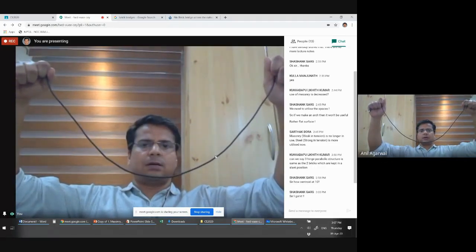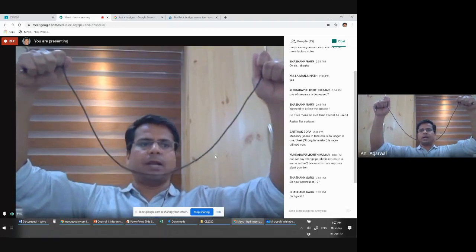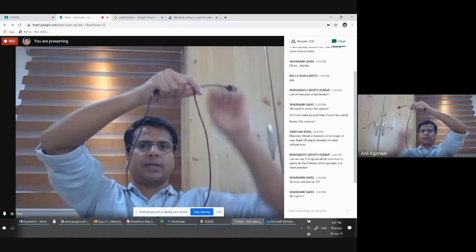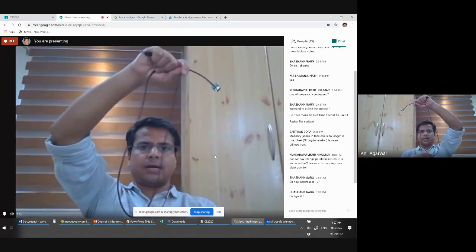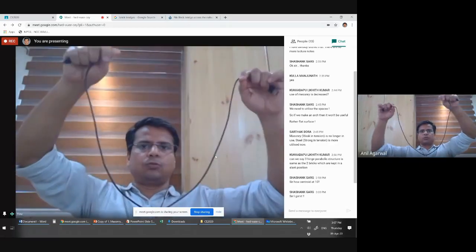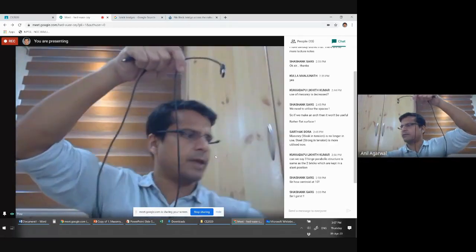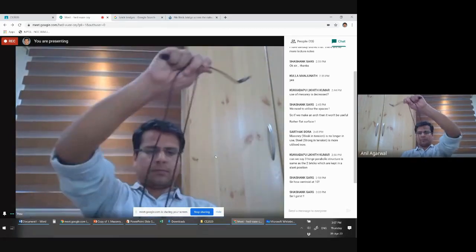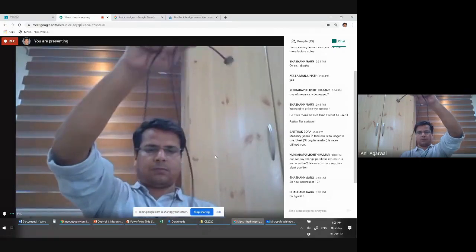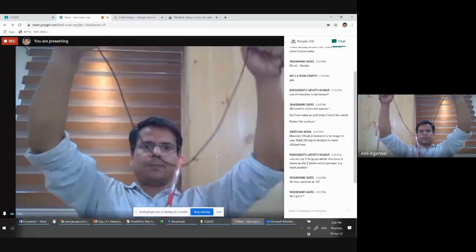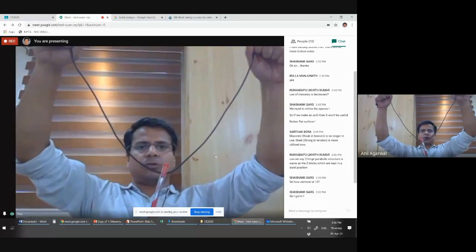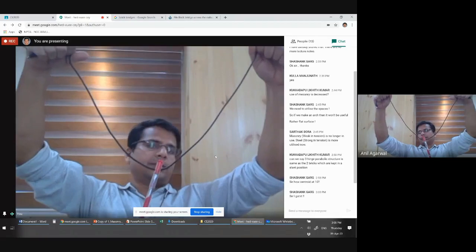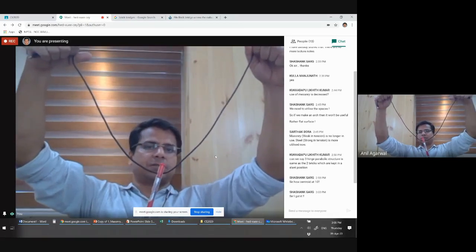But let's say you had a cable like this, and you hang some weight in the middle. Assuming that I'm holding it at two different places, and I hang a weight in the middle. How do I hang a weight? The weight is very small, but still you can see. The shape you got is one of the primitive arches, because if you have a perfect single point load, then it is a primitive arch. It's basically a truss, two straight lines.